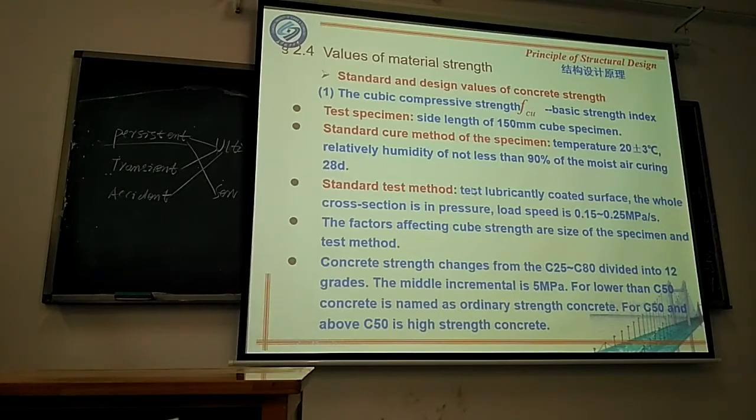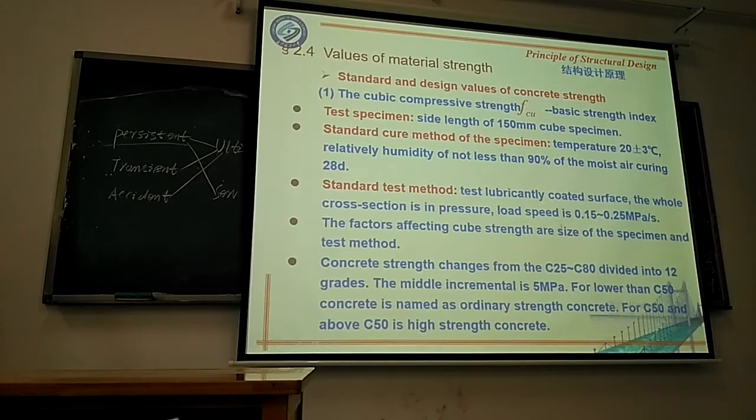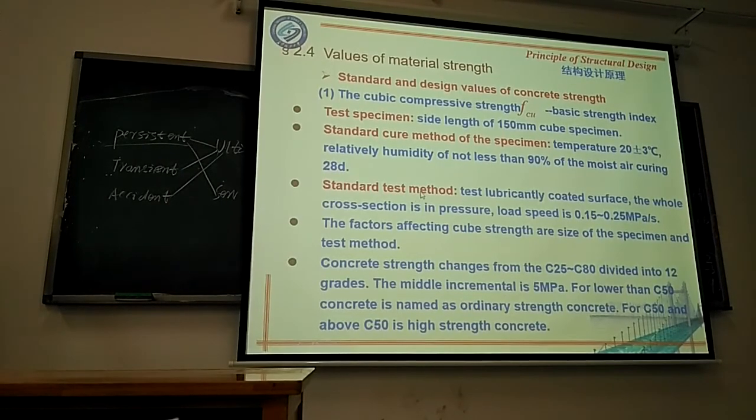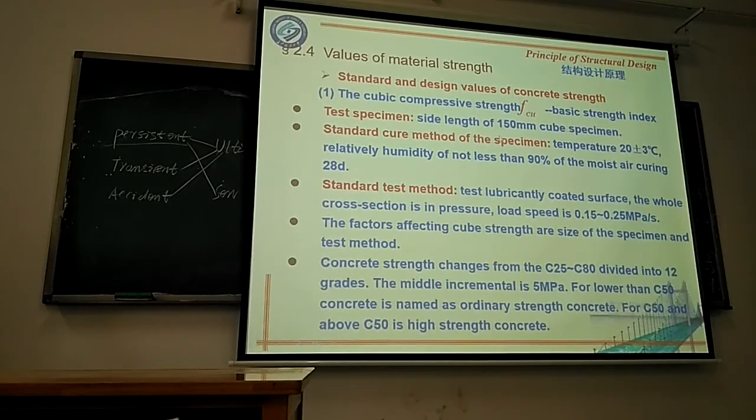In the test, lubrication is coated on the surface, the whole process is under pressure at a low speed. Then finally we get this cubic compressive strength fcu.